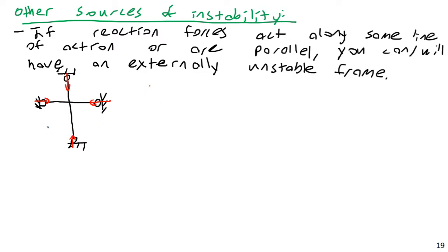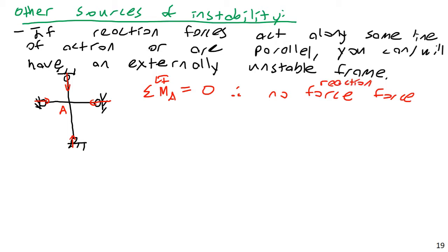So again, if I define this point as A, when I sum moments about A, I get 0. So therefore, no reaction forces to resist moments at A. And this thing will just start rotating.